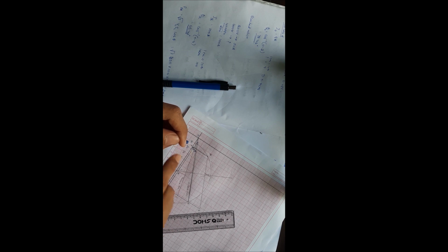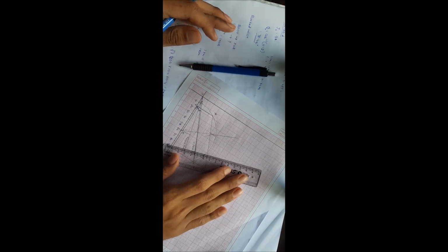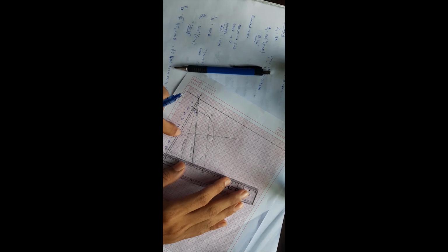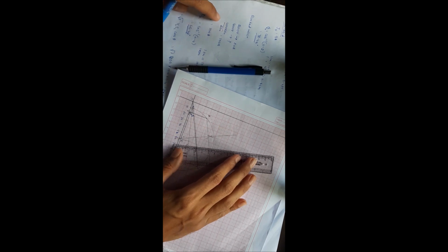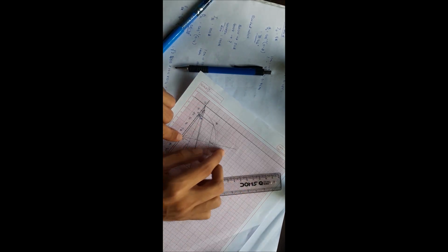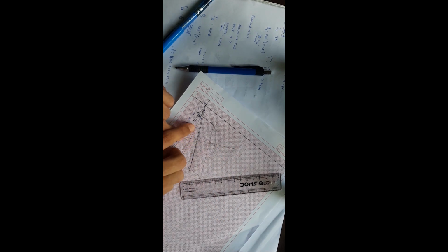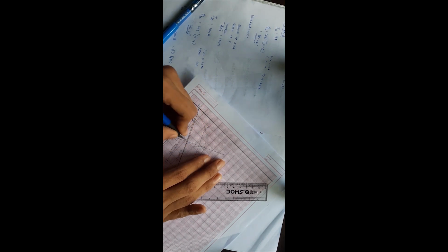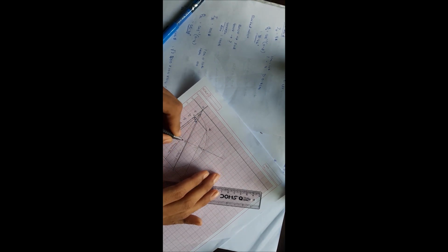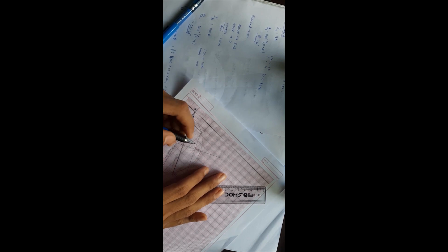After this, now we have to draw 2 lines from point C. One line is perpendicular to our output line, the other line is perpendicular to our torque line. So from point C, the perpendicular to our output line, in the sense it is 90 degree to our output line and is passing from point C, here we make a mark and consider it as M.